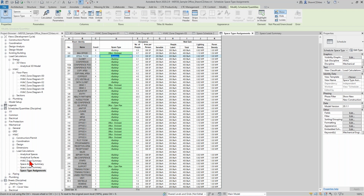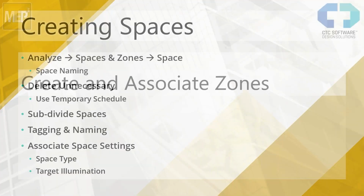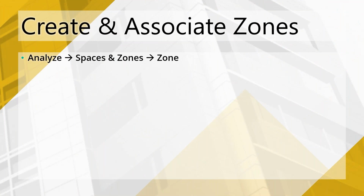Okay, the next schedule that we're going to be digging into here is actually this HVAC zone summary, but we don't have any zones yet. Our next major step is actually to create and associate some zones to these spaces that we've just placed. So what does this process look like? You're going to go to Analyze again. A lot of our work today is going to be on Analyze. Analyze, Spaces and Zones, same place we were for spaces, but now instead of making spaces, we're making zones.